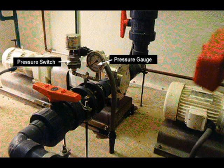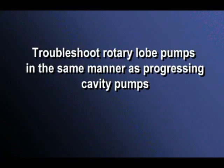As with other positive displacement pumps, severe damage or even dangerous conditions can result if a rotary lobe pump is operated against a discharge line that is blocked or restricted. It is a good design practice to include a discharge pressure gauge and a pressure switch to shut down the pump if high discharge pressures occur. Since the operating principles are very similar, the troubleshooting guide already presented for progressing cavity pumps also applies for rotary lobe pumps.